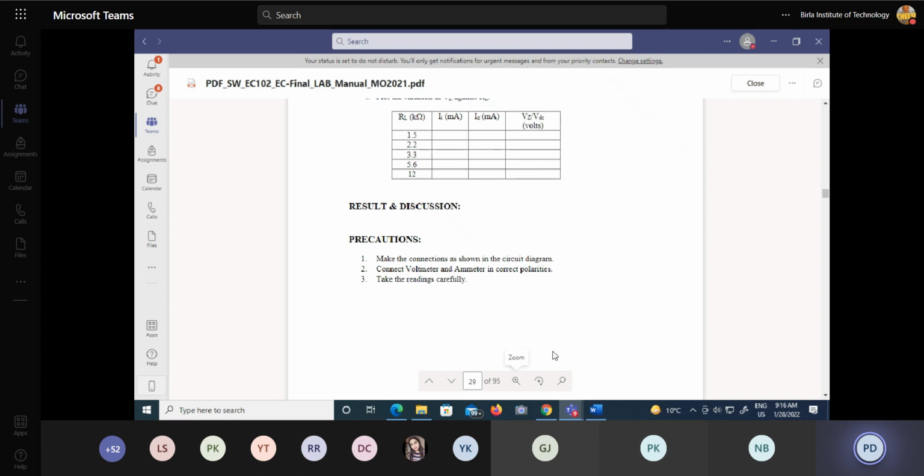One is due to the application of a very heavy electric field, and another is that if one free charge carrier, a free electron, collides with another, it will break the covalent bond and create another electron-hole pair, then they will hit others and again create further pairs. So in the avalanche process, the number of charge carriers gets multiplied, and at an instant when the minority charge carriers become very high, suddenly they cross the junction and your current increases very heavily. So that is the concept in your Zener diode.